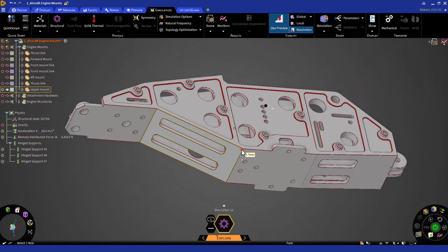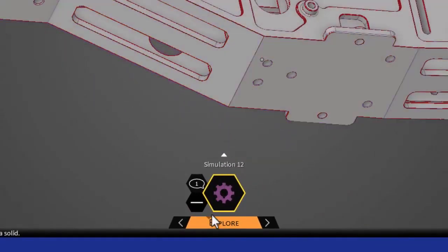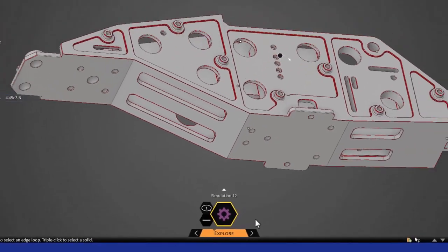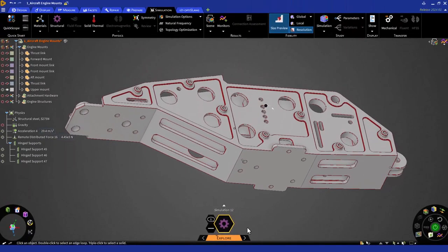To increase or decrease the fidelity, navigate towards the bottom of the window under the SID. Here, you will find the fidelity slider. You can slide to set the level of your fidelity, or, while over the slider, you can hit the spacebar and enter the fidelity value manually. The fidelity can be adjusted from 1 to 100. Set the fidelity to a level where you'll capture much of your geometry.